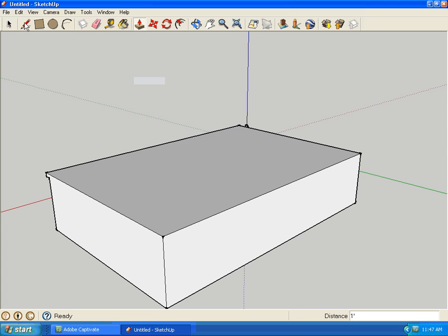SketchUp remembers measurements and is assuming that you would like to draw a line parallel to the one you made on the front side of the house. This is a correct assumption, so click on the red dot. Click on it once again and draw a red line across the rear face of the prism until it reaches the opposite edge. Once again, a red dot appears along with a flyout saying On Edge. Click on that dot.